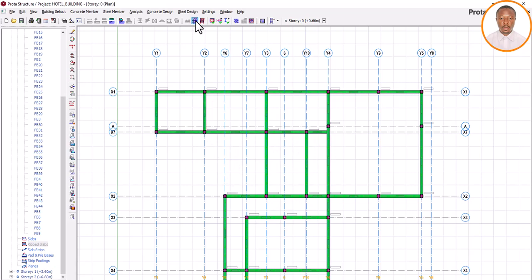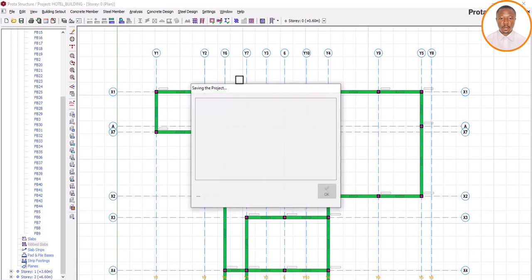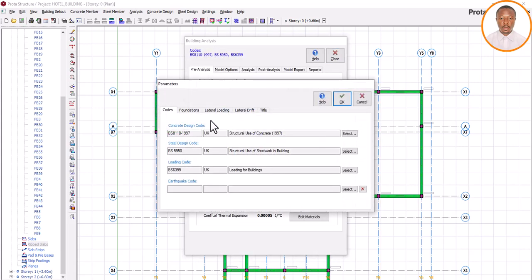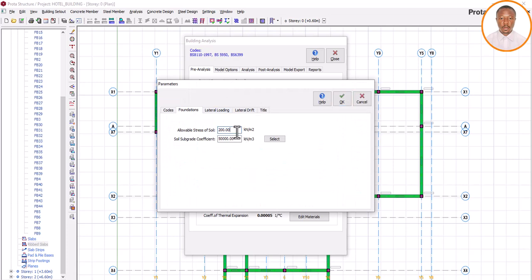Okay. So let me go back and now change my soil bearing capacity and see what will happen. Is that okay? So if you don't do this, make sure you always set this when it comes to wide strip foundation. Always input your value for soil bearing capacity. Is that okay? So let's assume this one is based on a geotechnical report, because I said I'm going to use the same structure to show you how to design your wide strip foundation. So therefore, let's say our geotechnical report is 95. Sorry, 95. Good. It's 95.